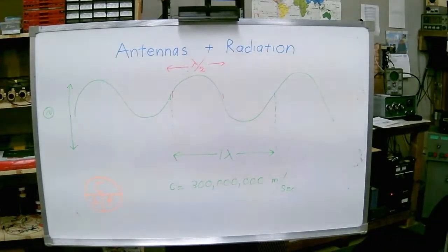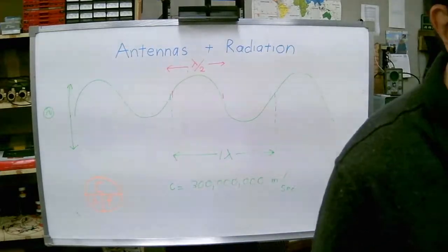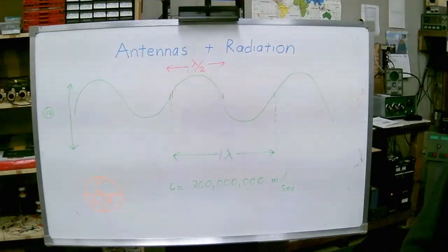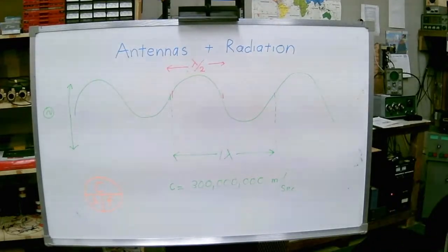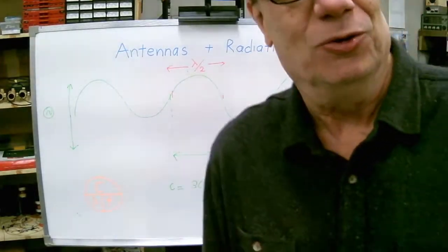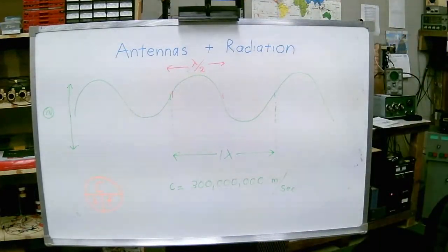The capacitance is distributed over a long distance, and any resistance we have will also be distributed. Most of the time, the resistance we're using in antennas is going to be this mysterious entity called radiation resistance, which we're going to describe in great detail, because that's going to be important to almost everything we do from here on out. But let's see.